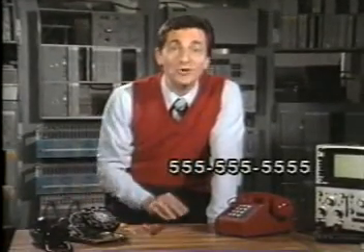In addition, DTMF dialing is much faster than pulse dialing. For example, the minimum time required to pulse dial the digit 5 10 times is over 6.5 seconds. Using dual-tone multi-frequency dialing, however, it is mathematically possible to dial the same number in less than 1 second.